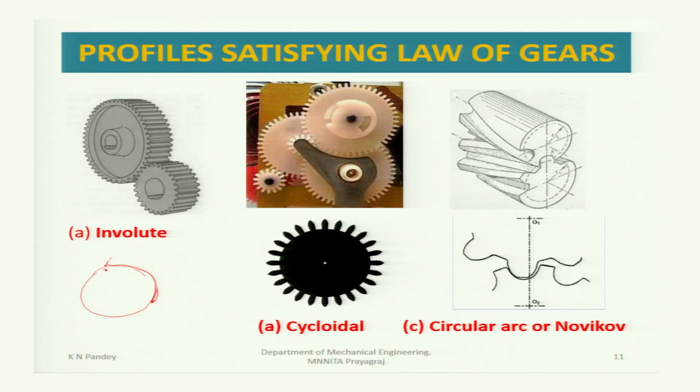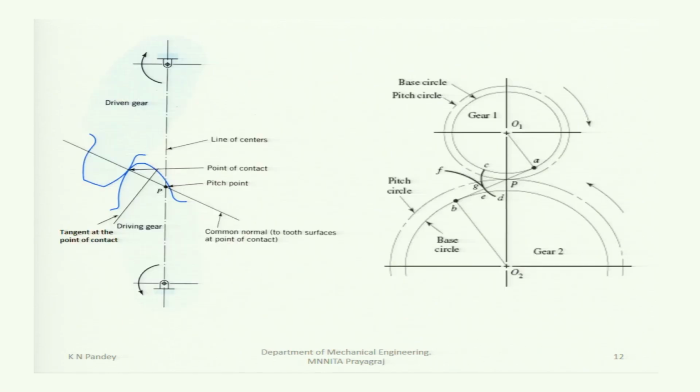Then the locus of this point P will form the involute tooth profile. This involute tooth profile satisfies the fundamental law of gearing, cycloidal also satisfies it, and the circular arc or Novikov also satisfies the fundamental law of gearing.